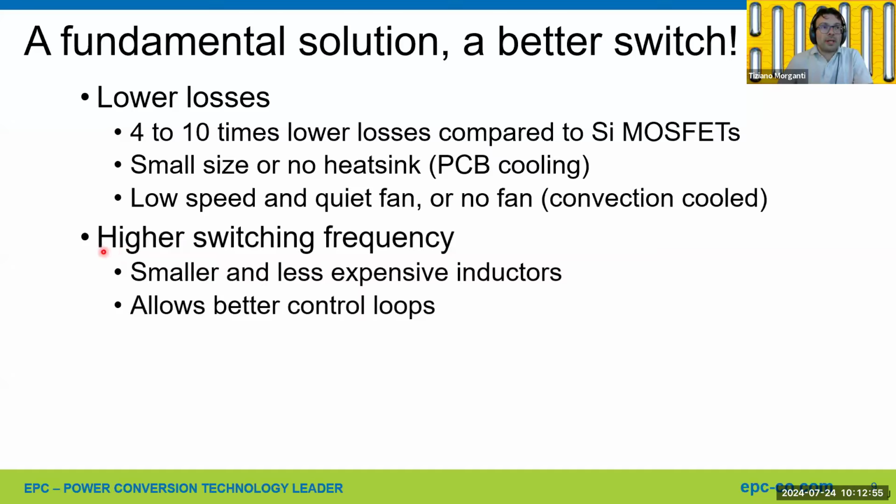Also, being very low in switching losses, we can achieve higher switching frequency. So we can allow the use of smaller and less expensive inductors, and also make it easier to implement feedback control loops with very good control over the whole audio bandwidth.